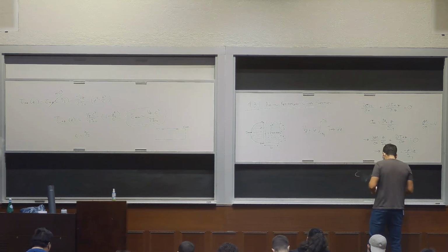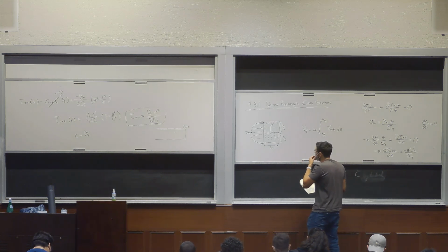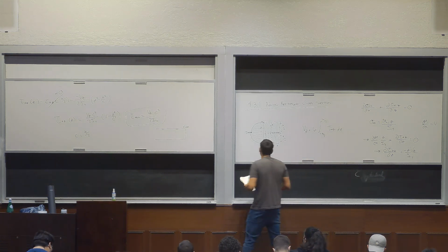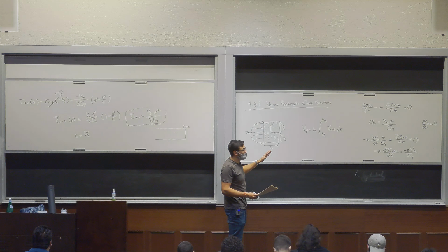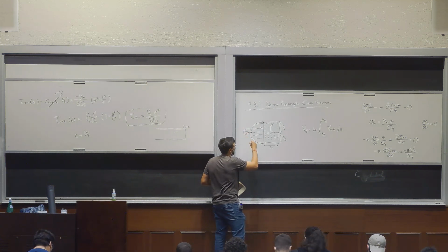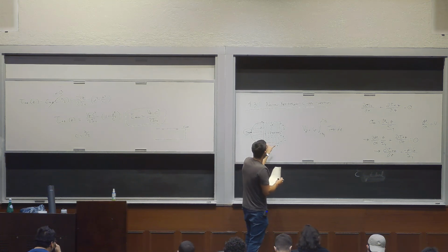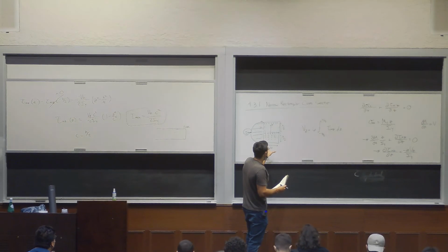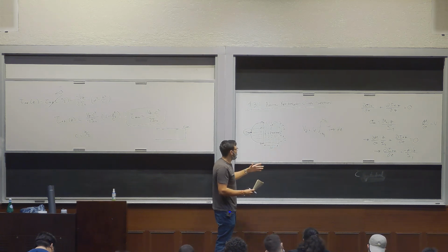Okay, so that's it for the narrow rectangular cross section. It's the simplest case because the distribution in the y direction is assumed constant, so we don't have to worry about that. So we can always solve for tau. However, there are sections where this dimension can't be considered narrow, and therefore there's going to be some distribution in the y direction.